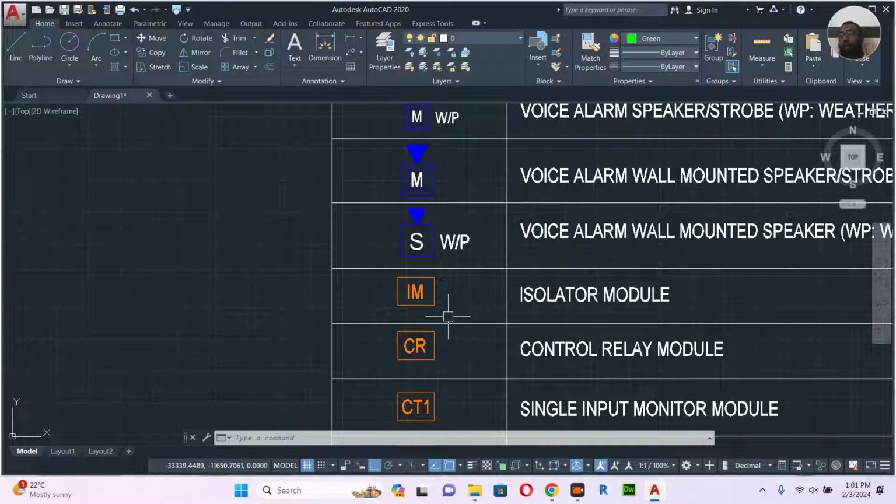So there is a situation that comes when you are designing a fire alarm drawing. Every 20 devices you should put one isolator base. This is a standard, a designing standard. But this isolator base only comes for the detector. But say your 20 devices are control modules, or your 19 detectors are monitor modules. Mostly in my project they told 15 to 20 between.